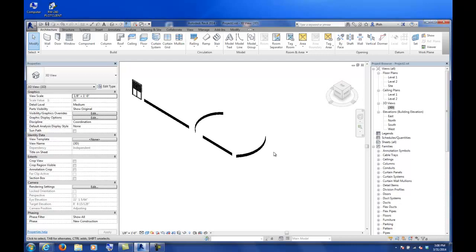Anyone modeled railings and stairs in any other program, like Rhino or SketchUp, I imagine? Basically you create a section of the stair you want it to look like. You have to add it up and make sure you got all the right treads in there, and then you extrude it some distance, or you do a sweep to get a pattern. With the railings, you draw some kind of line, host a section profile to it, and then sweep it all the way up your stair. That's basically the same concept, but we're going to be doing it in dialog boxes. So we'll try to make that comparison as we go.